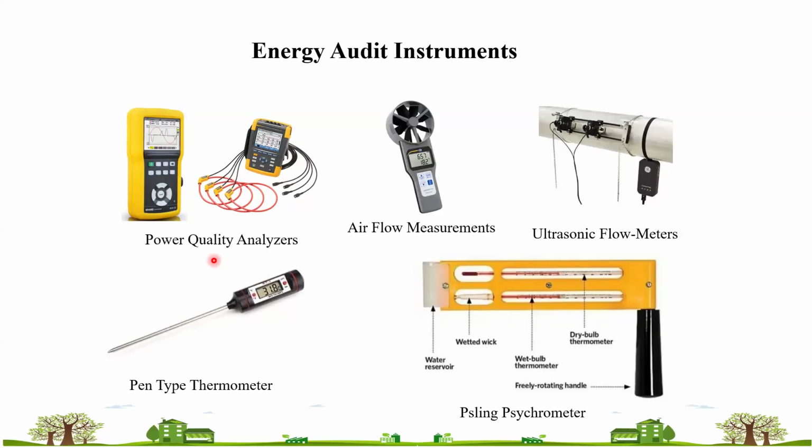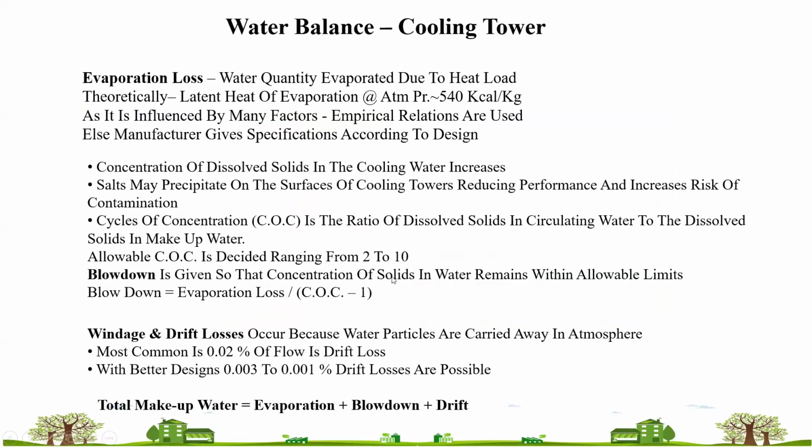Then another is that your nozzles are not spraying the water in the cooling tower as per desired conditions. Another probable reason can be water quality. You are not maintaining the water quality as it has to be maintained. If you maintain too much TDS in the cooling tower, your nozzles get choked. That's how the performance of the cooling tower drops.